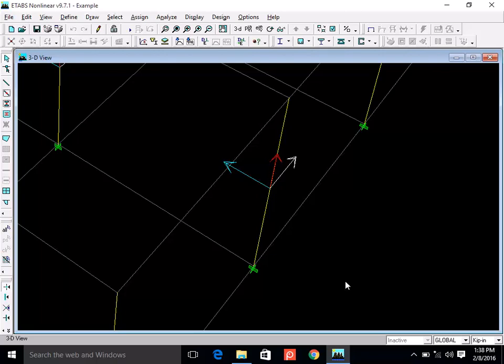Okay. So the point I want to make is that you cannot make a universal statement that an edge column is always a uniaxial column. Generally it is, but when there is unsymmetrical loading or unsymmetrical dimensions, then an edge column may also have biaxial bending. Okay. But in this case, for example, this column, if this is of concrete, then it won't have. It will be a uniaxial column. I don't see much of a difference on either side.